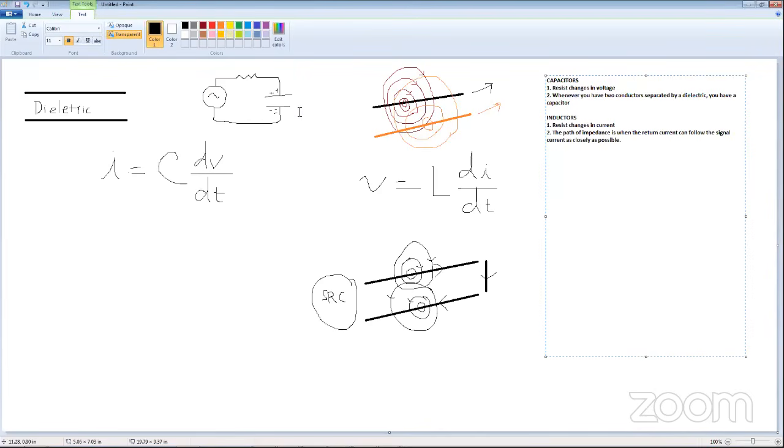Okay, in the case of inductors, you do have to worry about mutual inductance because the magnetic field lines can overlap. So you'll have the inductance of the wire itself plus any neighbors that are interacting with it. Simple rule of thumb, if you want to minimize inductive coupling, whatever the thickness of the traces is, make sure that's the separation between them. So if you have 10 mil traces, then you want to make sure that between any two traces, you have 10 mils of separation. In doing so, you can minimize any inductive coupling.